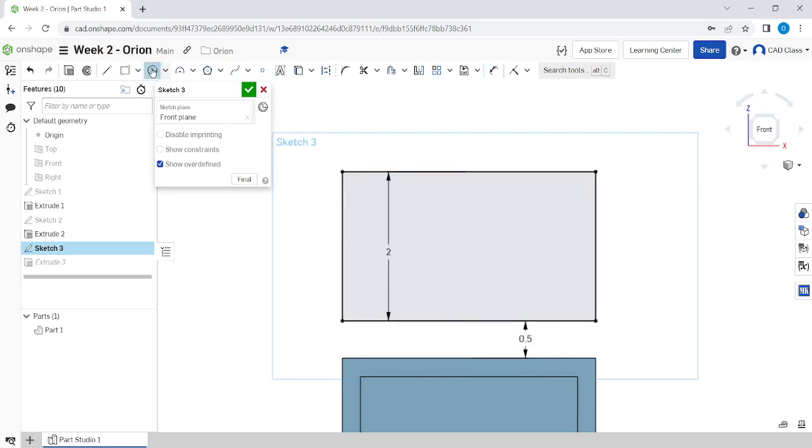So I can select the circle tool, place down a circle, place down the second point of the circle, and then this is just waiting for me to start typing. So I can type 1.25 inches and then press enter, and it will automatically place this dimension. And I can move the dimension around after the fact, but this auto creates a dimension for us. It's the same thing as if you went up and created a dimension using the dimension tool, but it just does it for you. So that's super useful. That works for rectangles too.